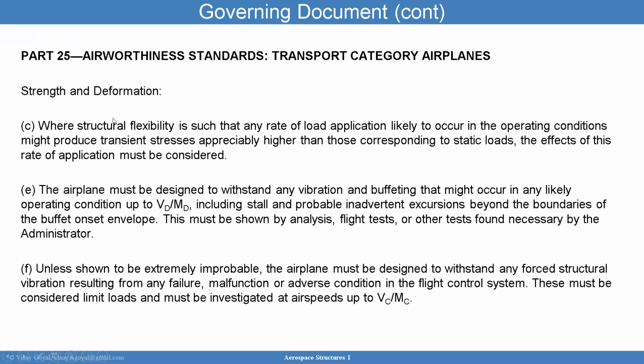And here we have that we need to show that where structural flexibility is such that any rate of load application likely to occur in the operating conditions might produce transient stresses appreciably higher than those corresponding to static loads, the effects of this rate of application must be considered. So anytime the rate of load application can be problematic, we have to show those effects.